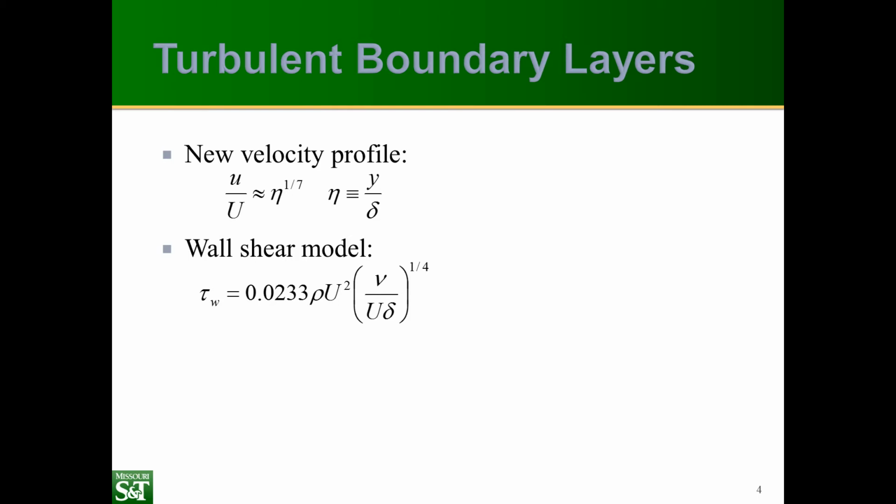So once again, we're just going to analyze a flat plate. So the basic assumptions are the same, and the final equation is going to be the same. We've just changed our velocity profile for the definition of theta, and we have a different expression for wall shear, tau w. We also have a problem with our boundary condition, where we start, delta at x equals something. Now we're going to analyze this case by assuming that turbulence is tripped at the leading edge of the plate. So delta equals 0 at x equals 0. And then the whole thing is turbulent.